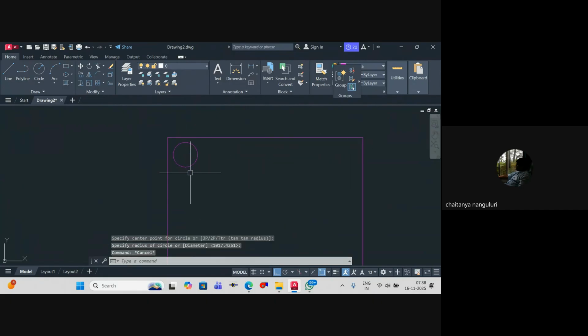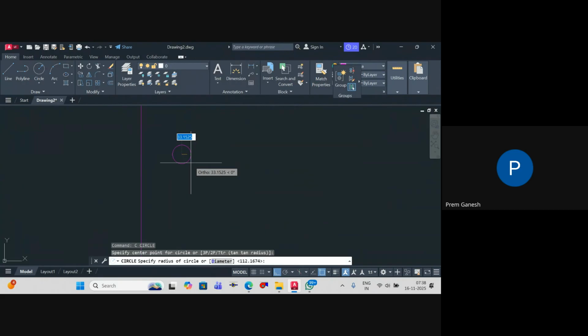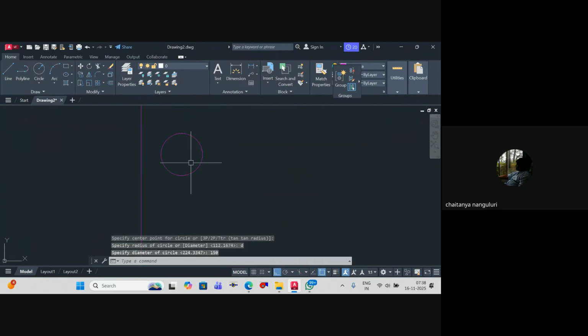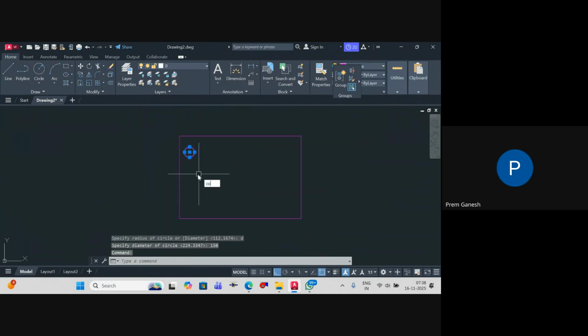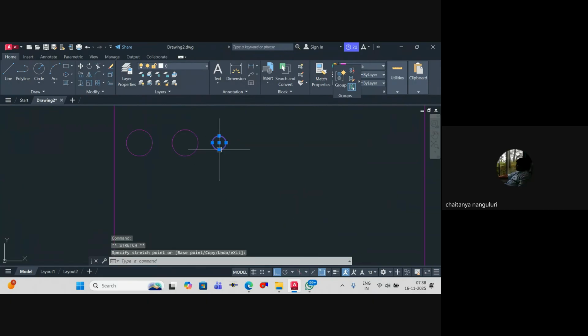After all, how much do you require? One hydrant pipe you require. How much diameter is it? It's around 100 to 150, the diameter will be 150 max. And you require one more pipe, which is your sprinkler pipe. You will also require one more drain line. Three pipes you require.